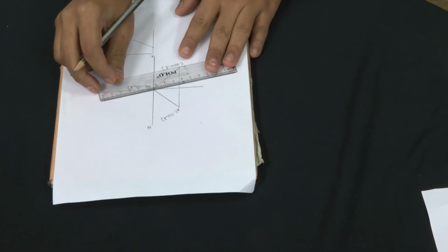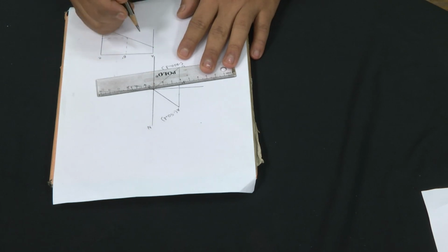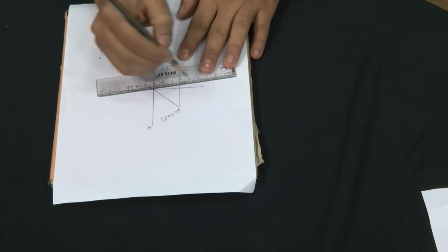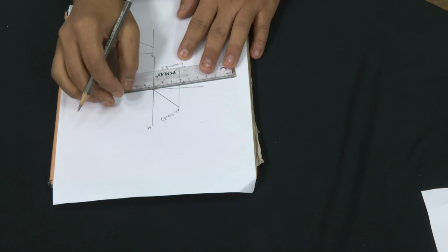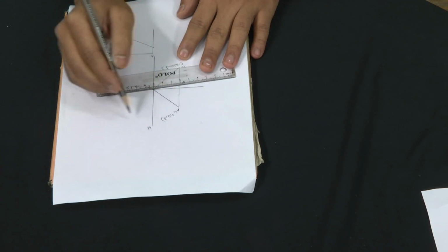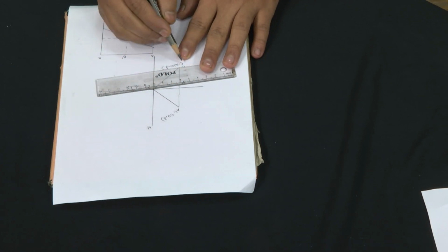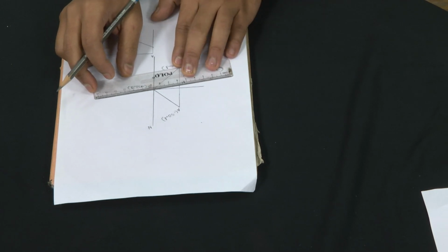So, clearly now if I join B with this point B dash, I would get the minus 130 meter strike line, and then if I construct a parallel line, any parallel line to the corresponding 130 meter strike line from the point A or from the point C, we will get another strike line. From point A if we construct, we will get a strike line of minus 50 meters. If from point C we construct, we will get a strike line of minus 220 meters.